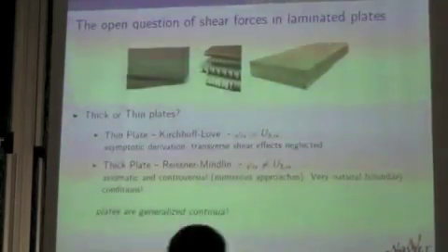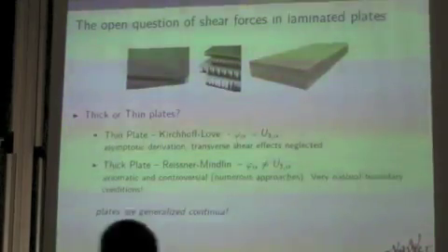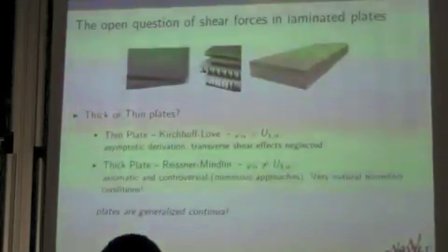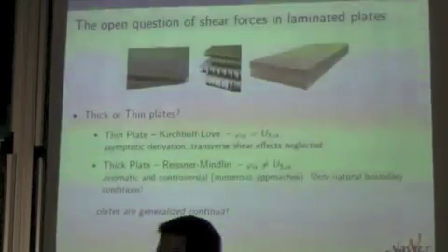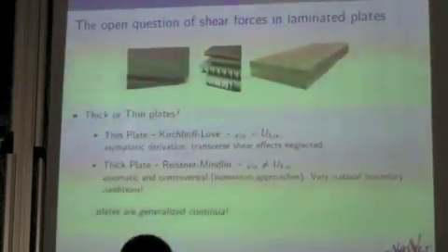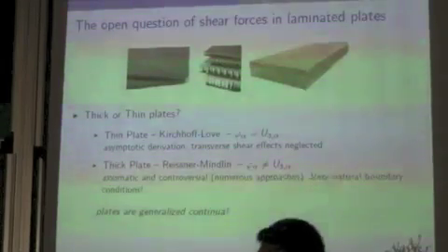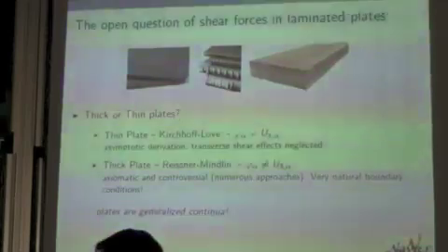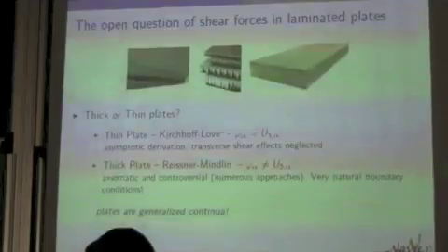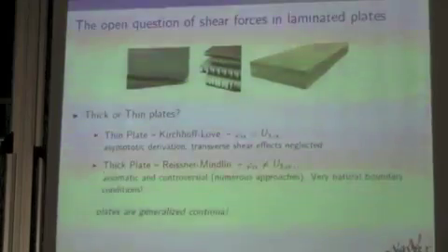Since you need to go higher order to have transverse shear effects, the Pandora's box opens. And this is why plates are generalized continua. Most structures are generalized continua, because there is the relation between the shear forces and the bending moment. Since the shear forces are the derivative of the bending moment, you have an internal length scale, and so it's a generalized continua. The engineering model for thick plates is a Reissner-Mindlin plate model.